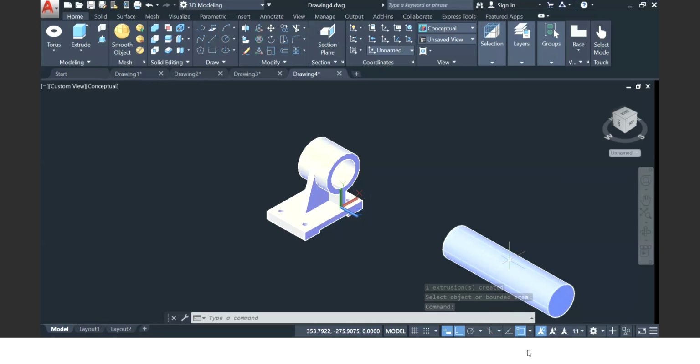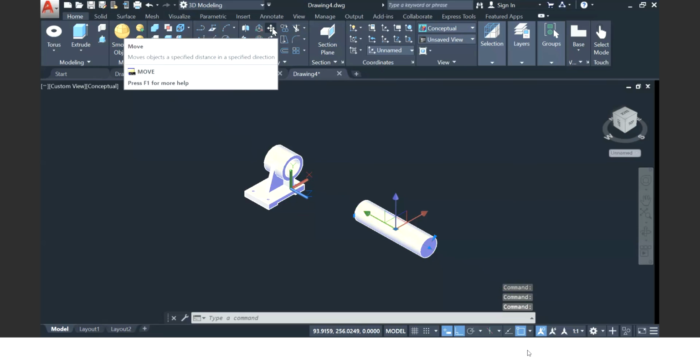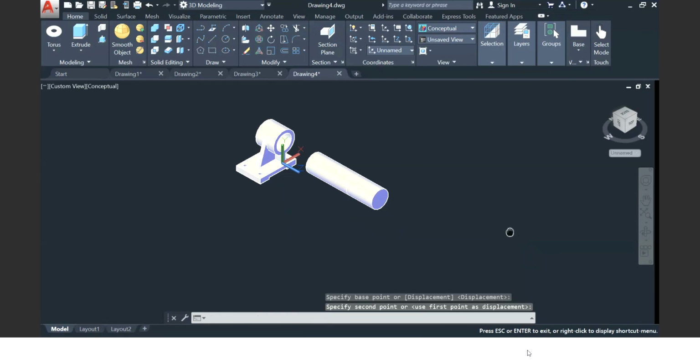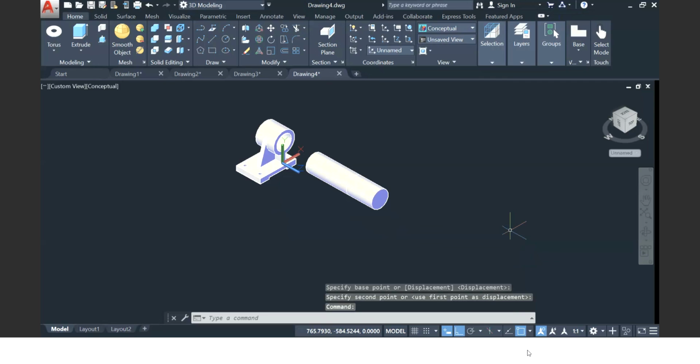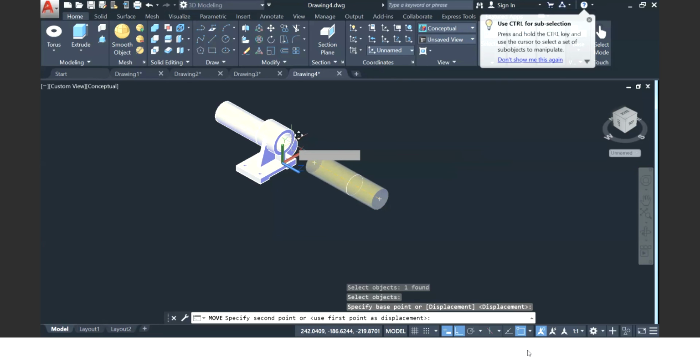So in one particular drawing later on, you need to arrange all these components to be aligned in one axis to show the exploded drawing. You align everything to become one. Then you arrange this component, for example, you move this component to be exactly from here, it's supposed to be in there.